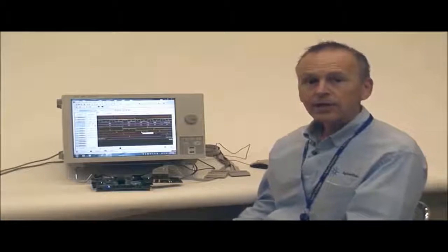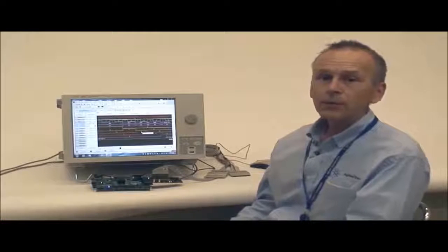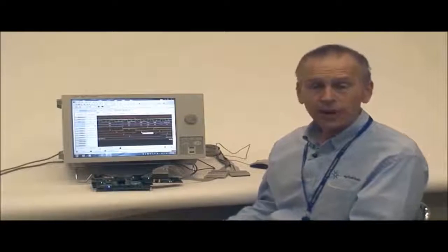I think you've seen how high-speed timing capture, and in this case 5 GHz, combined with deep memory, allowed us to trigger on a symptom, which was a timeout flag, and then look way back in time to the point where there was a root cause of failure. And in this case, there was no functional problem with that state machine, but there was a timing problem between the clock and the data bits of that state machine.